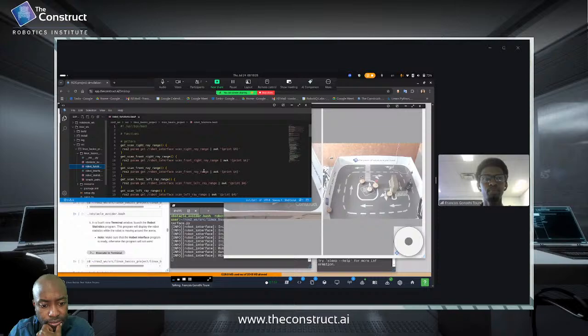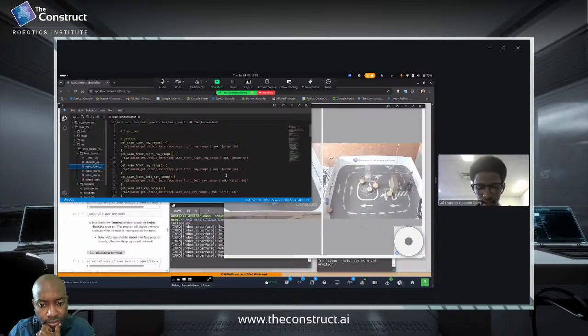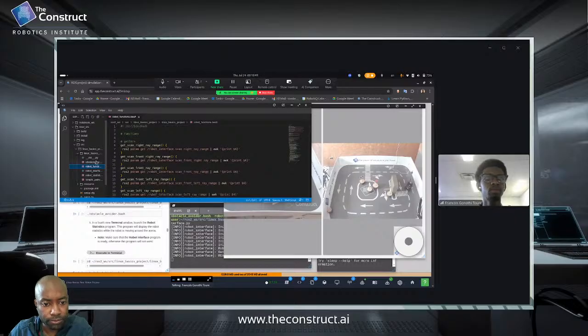And after initializing it to 0, it sets the threshold to 0.3 meters, which is what we've already talked about. And the LiDAR sensor is going to scan values and read them using the function wrappers, what I was showing in the beginning of the code, not here, but in the obstacle avoider.